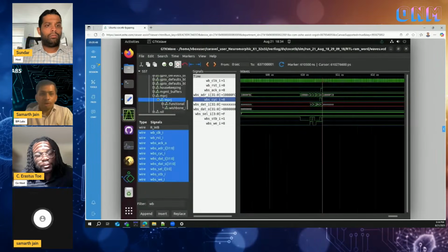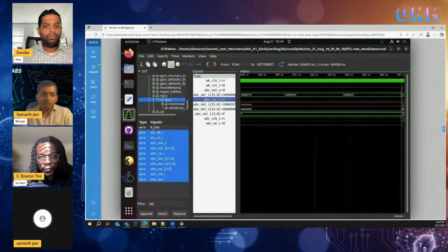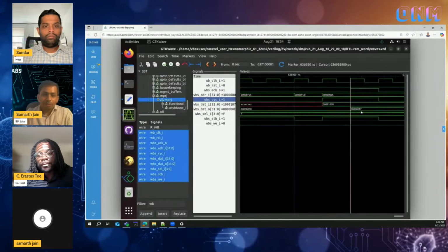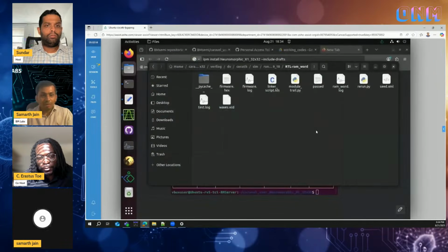And then I want to program that memory because the memristor is a memory element. So then I will put data into that. For example, I want to store 1 into it or 0 into it. So that will be the data component. So once I write that command into the write bus, x coordinate, y coordinate and the data, it will store that data. Then later on, I can come and do the read cycle for it. So the data will still be there even if the power is gone, because it's a non-volatile memory. It's not like SRAM where if you turn it off, it goes away, right?